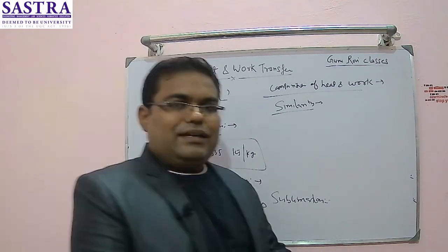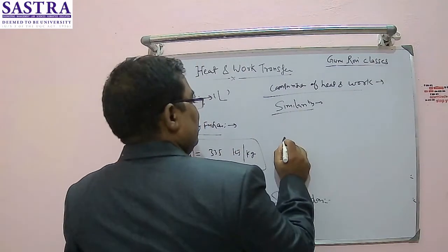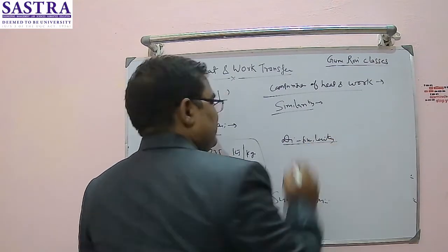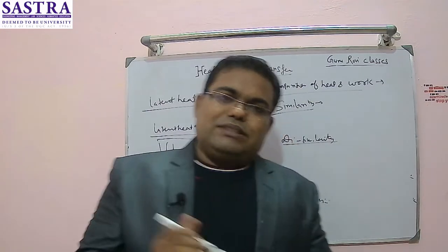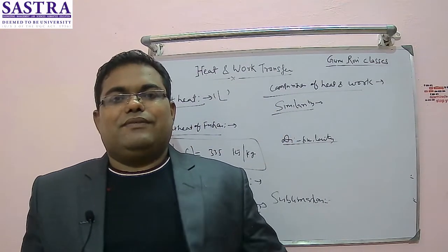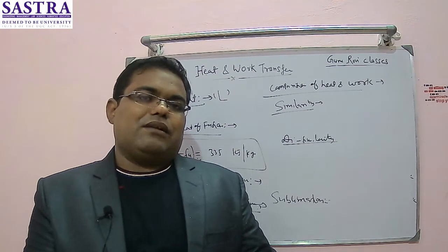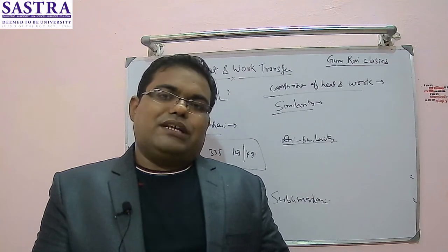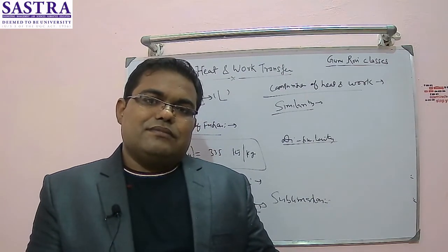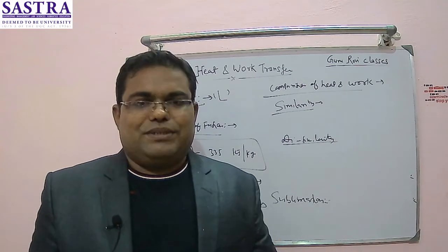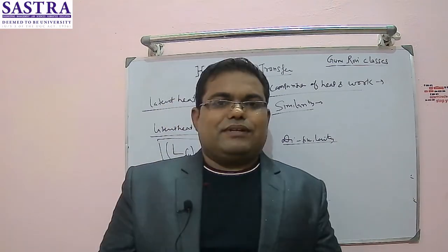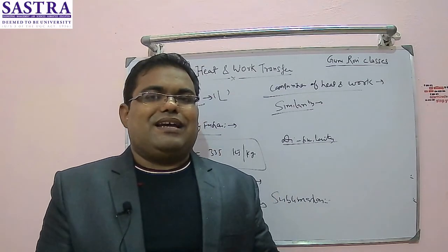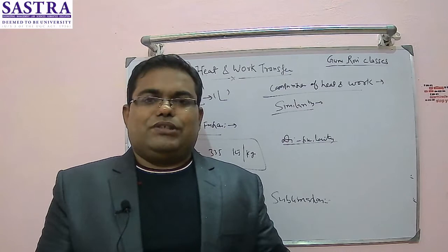If we look at the dissimilarities, the first and most important dissimilarity is that heat transfer will occur only when there is a temperature gradient, and work transfer will happen for all the changes except the temperature gradient. So whenever there is a temperature difference, there will be only heat transfer, and apart from temperature difference, any phenomena, any changes happening, will be termed as work transfer.